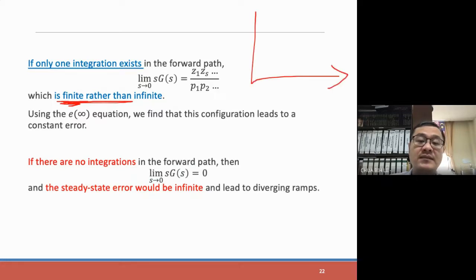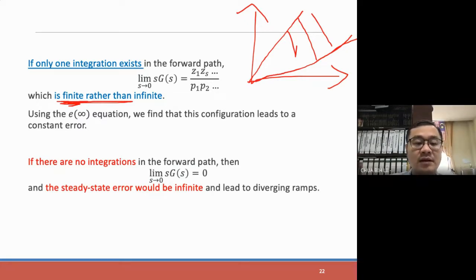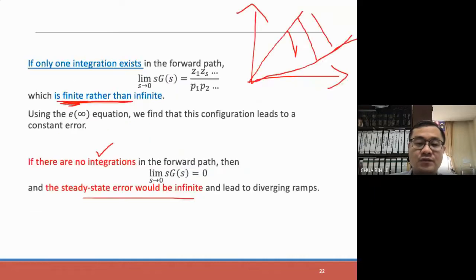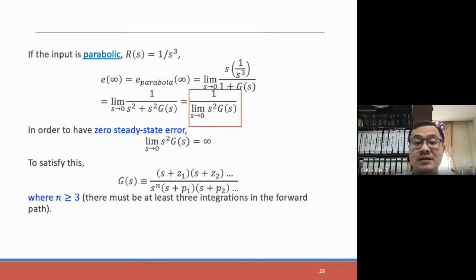you will start to see a continuously increasing steady state error occur. So the kind of infinite steady state error, or non-zero type of steady state error, will occur in that form. If there are no integrators, the steady state error would be infinity for the ramp input. You can see that it continuously grows, and there is a relation, a shape, that you may later observe.